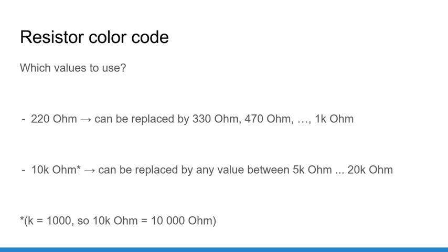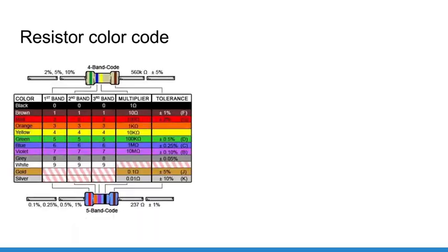And now that you know what values you need for the resistors, the next part is to know what resistor to pick using the resistor color code. As you can see in your resistor set, the value of the resistor is not printed on it. Instead, you get 4 or 5 color bands which you have to interpret. Don't worry, this is not difficult to do at all, and I will give you a few tools that will assure you that you don't make any mistake. First, here is a table showing you what color corresponds to what number and in which order.